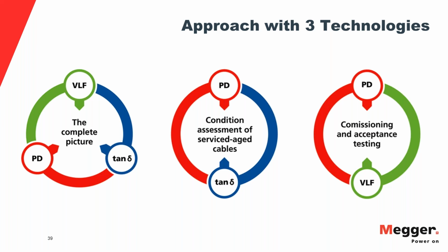Now, interestingly enough, when you do the tan delta test, then also in IEEE it is U0 again, and this can cause the paradox situation under certain circumstances that the tan delta in IEEE can be carried out at higher voltages than the actual withstand, depending on which numbers you use.